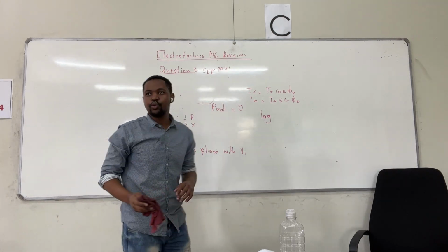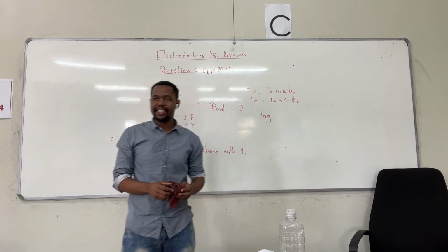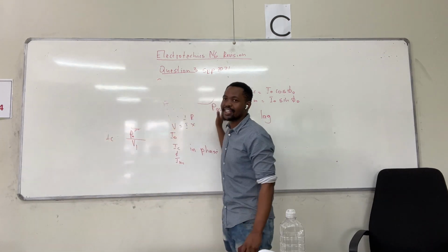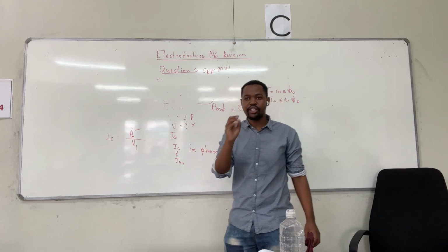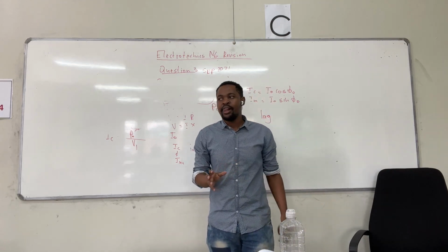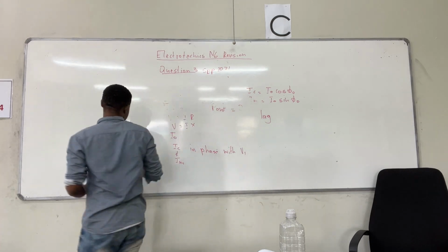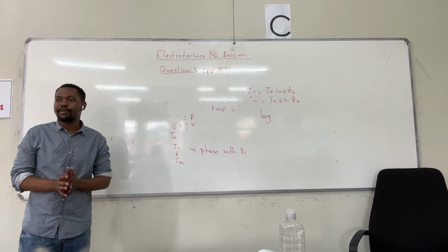Please, guys, those who are not here, I'm going to explain the open circuit test. The open circuit test is based on a transformer on no load. The open circuit test helps you calculate iron losses. We did it yesterday. After I've explained this, it's not really that difficult.